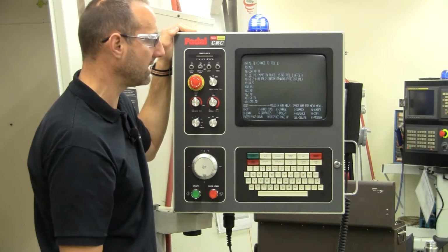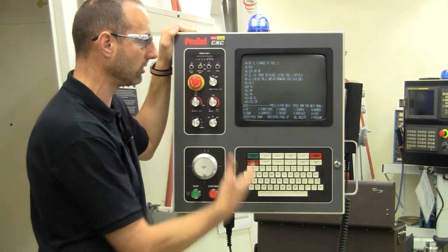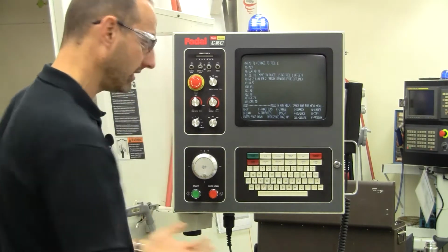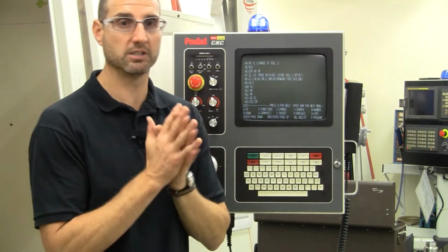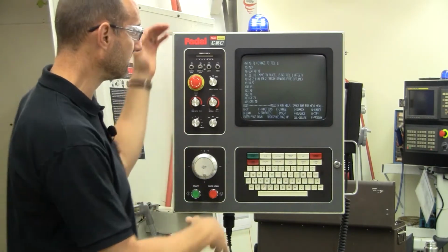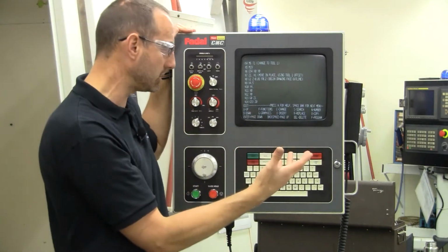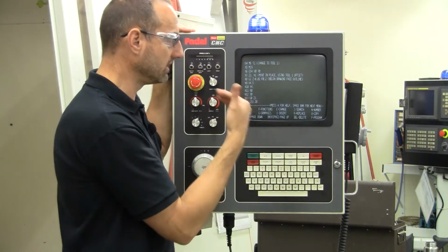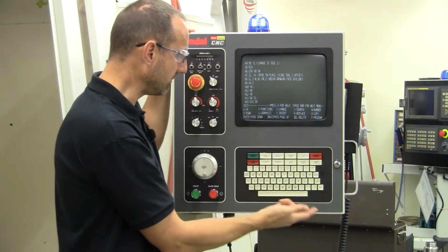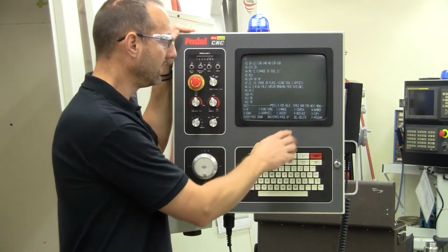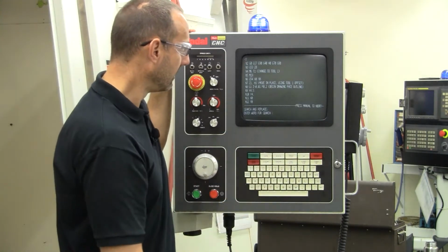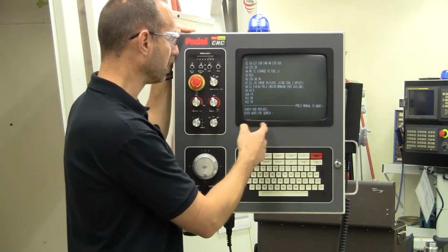Another thing that is typically done on the controller is maybe I want to change my feed rates. I'm machining along. I found that my machining feeds are either too fast or too slow, and maybe I want to change all of those. So instead of having to search through and find each particular feed rate, there is essentially a search and replace function. Same sequence. I'll press T for top, and then I'll do the replace function. So R.